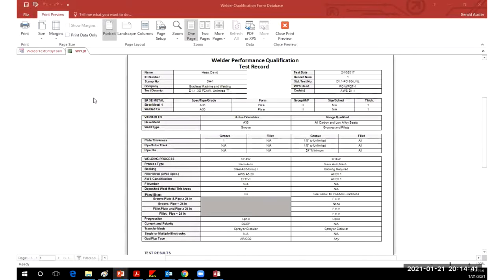There's a whole lot of different aspects to welder qualification testing that I've never even dealt with in D1.1. I've done some D1.3, D15.1 for the railroad code, D1.6, and a little bit of D1.2, which is an adventure. But overall, it's all about getting the applicable code book and looking through it, finding out what it says, and not making assumptions about what they did on the last job, or what you think is good because they told you in CWI school that it was good to not have a weave bead. You have to look at what the actual requirements are and just follow those.